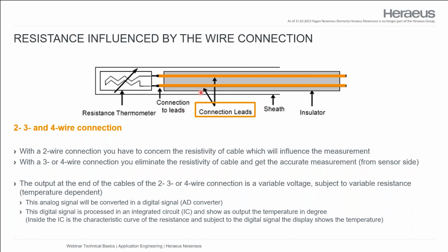It's not a problem if you use typical wire lengths, smaller than, I don't know, half a meter or so. But it gets more and more important if you have wire lengths of 2 meters, 10 meters, which is really sometimes possible in the application. Then you have to take care about the wire lengths, and in the end the failure you create with that wire connection. But sometimes our customers need a 10-meter wire or cable. Then you could use a 3-wire or 4-wire connection to eliminate this failure.